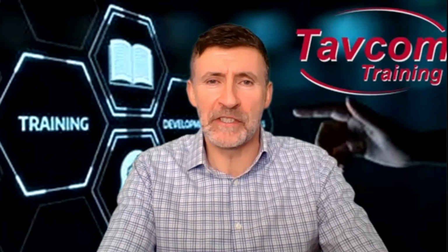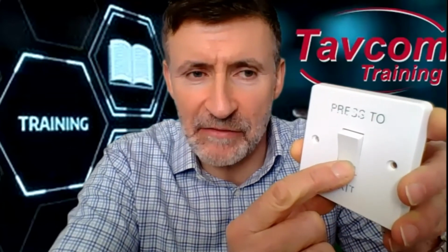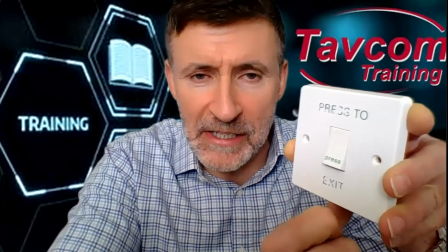This is because it relates to both intruder and access control. So with a few slides from my training courses and a little bit of show and tell, let's start with this subject. I'm going to start by explaining relays and comparing them to a simple switch. As you will see here, this is typically what is used to exit a door for an access control system. When I press the switch, it is changing the state of it from either normally open to normally closed. When I release it, it goes back to its original state.